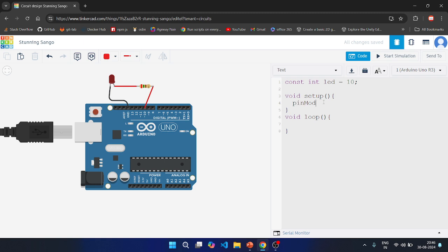And we should declare a pin mode which says whether the pin should be expecting an input or an output. And every line in Arduino Sketch programming language must end with a semicolon. The pinMode function takes in two arguments, the pin number, which is 10, but we don't need to do it because we have declared a variable called LED, and the type. It's an output, and OUTPUT should be written in all caps. Arduino Sketch programming language, like other programming languages, is case sensitive.